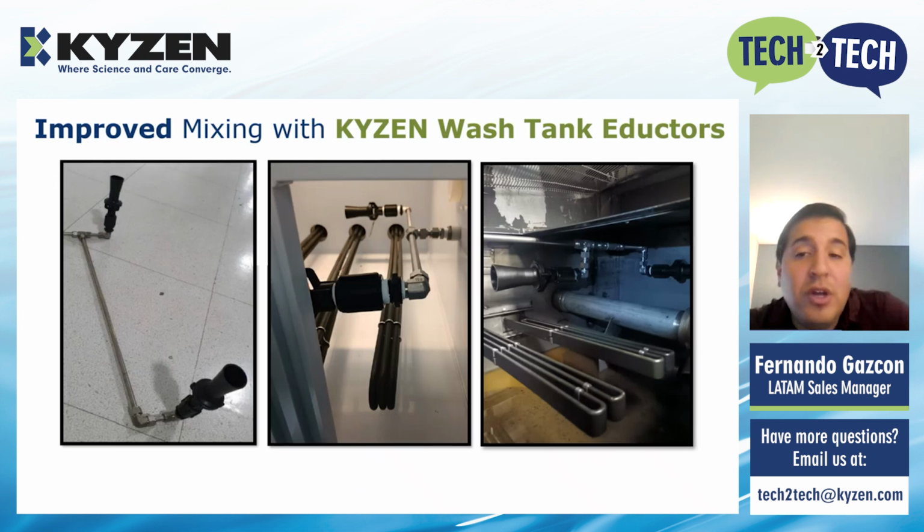After determining the root cause of the concentration percentage issue, we recommended the use of KYZEN adductors. These are essentially flow blowers that are recirculating the liquid inside the wash tank, creating extra turbulence in the desired areas to ensure an appropriate homogeneous mixing of the solution. After adding the adductors to the system, the concentration readings stabilized and the extra addition of chemical to the system